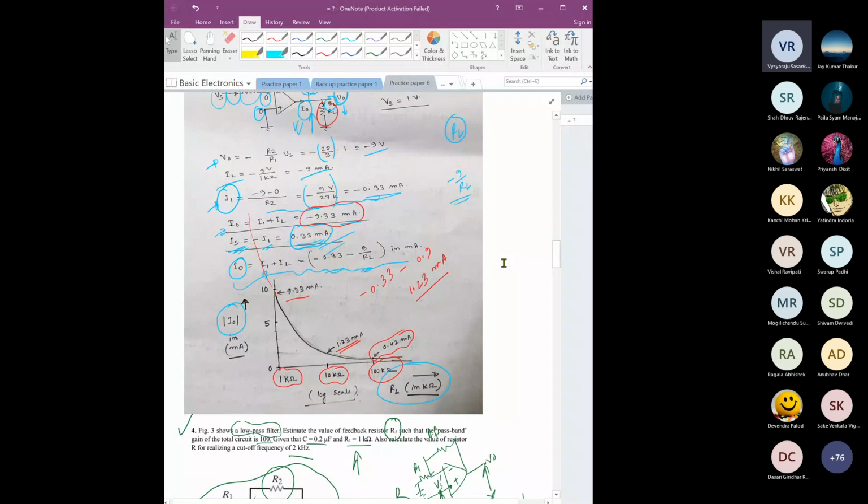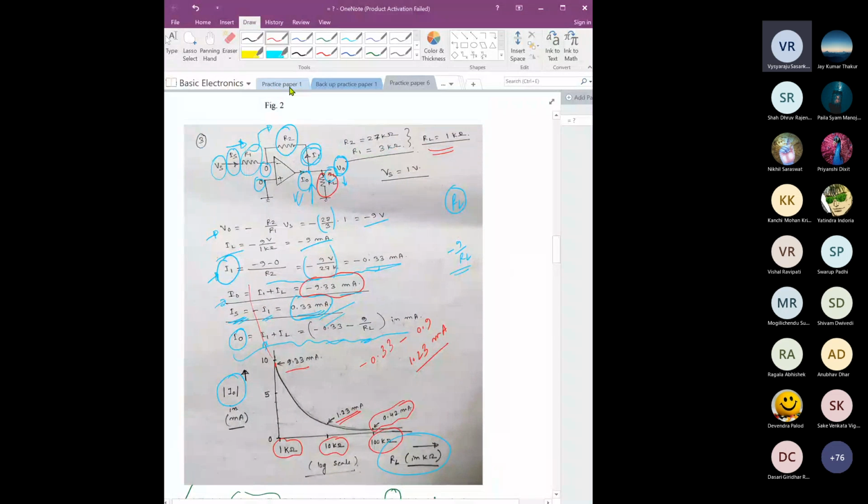I thought you would understand it. Okay, see this one, right? This problem. Let me, I don't have any extra color. Okay, so here this is I naught 1 versus this RL, right? So what is I naught 1? I naught 1 is the current that has been supplied or sunk by this op amp, right? See how I naught is dependent on RL, right?